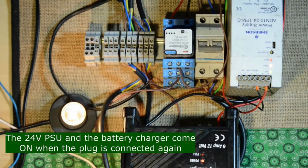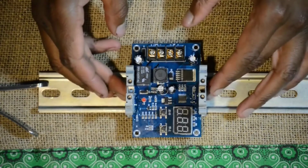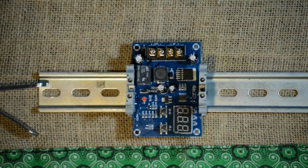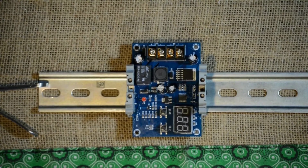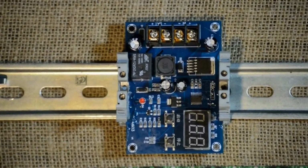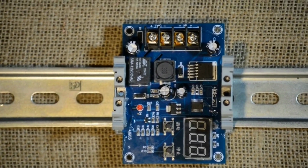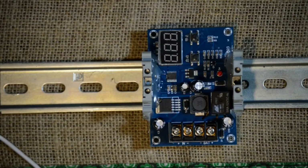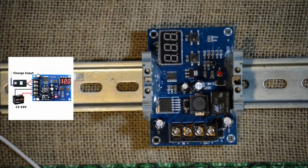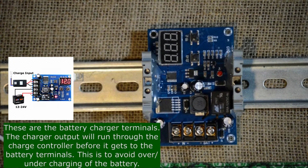So in this section, I'm gonna connect the charge controller, because if I don't use the charge controller, my charger is just gonna continue charging the battery, and that's gonna damage the battery due to overcharging. So what I'm using here is this XHM603 DC battery charger. As you can see, you have the in and then you have the battery.